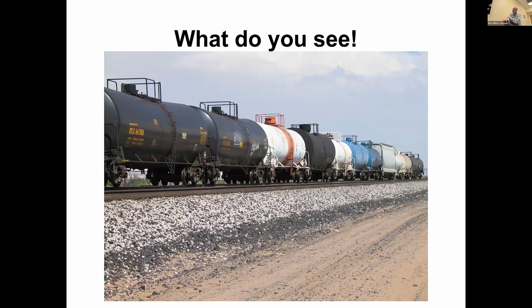But before we start reviewing it again, so what do you see here? High pressure, low pressure. This is where you're going to practice out on the street. How do we tell a low pressure car? When we look at the top, we see multiple things on top, from 2 to 4 on top. Pressure cars, we see one thing only. And again, you're going to see modern low pressure tank cars look more like a pressure car because you're going to have one big valving housing on top, and you may not see the manway opening there and stuff like that. So it's easy to make a mistake in that situation.